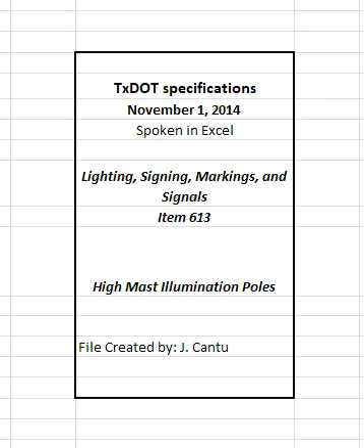Provide circumferential welds only at the top attachment and base plates. Grind or smooth the longitudinal seam welds to the same radius as contacted shaft corners for the length of the lap plus at least 6 inches at each slip joint splice. Ensure acceptable seam weld profiles for the remainder of the pole exterior. Provide full penetration longitudinal seam welds for a length of 1.5 diameters plus at least 6 inches in outer sections at splices and base plates.